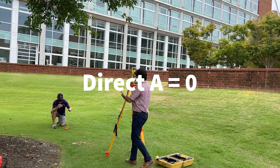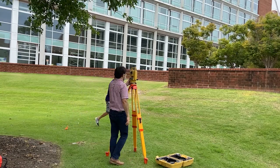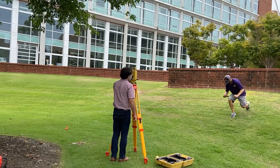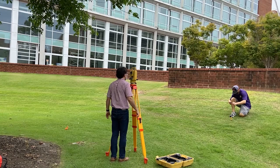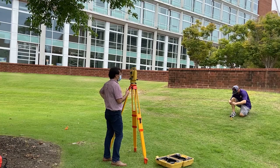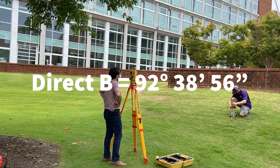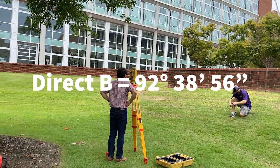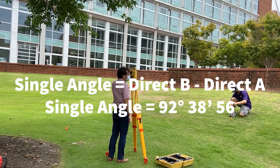You started from the point on the left side, then you go to the right side. So you ask your rod person to hold the prism on the point on the right side. Once it is in place, you look through the telescope, find the string, match the crosshairs with the string, and then read what you see on the screen of your total station. My reading is 92 degrees 38 minutes and 56 seconds. This is my single angle.